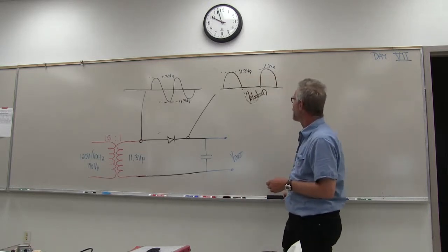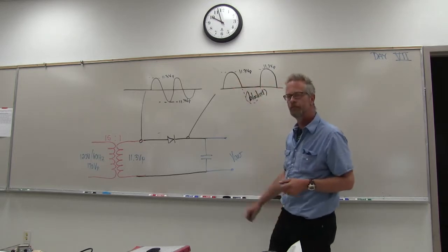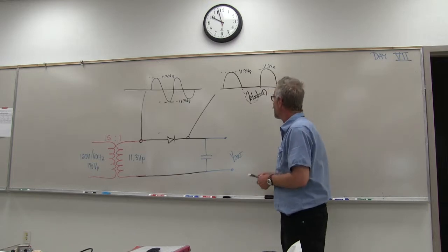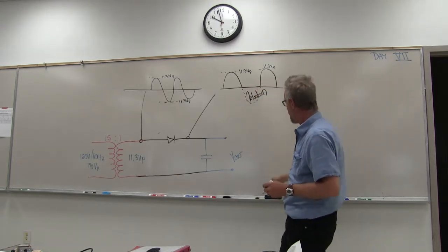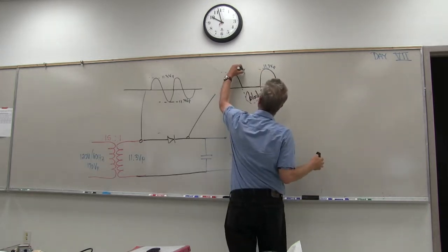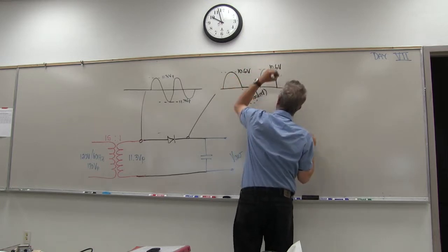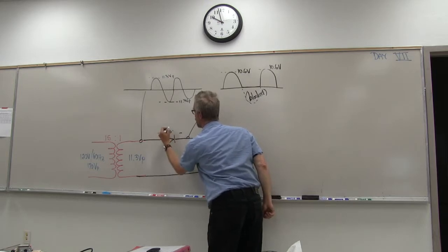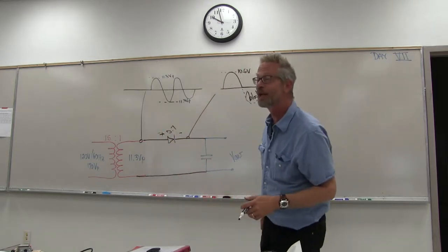So we're doing the Humpty Hump thing on the outside of the diode. We just have a sequence of 11.3 volt humps. And actually, that voltage is not right. It's actually going to drop 0.7, so 10.6 volts, because of the plus or minus 0.7 across our diode. Remember, our diode doesn't do its work for free either.